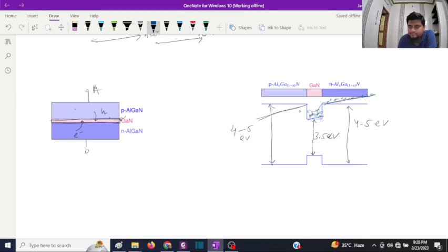Lot of electrons. Likewise, holes will follow the bubble model, and they will be collected only in this region, the gallium nitride or the active region, because there are a lot of carriers in a particular region, and that's why a lot of light will be generated from this active region. So that was electrical confinement.